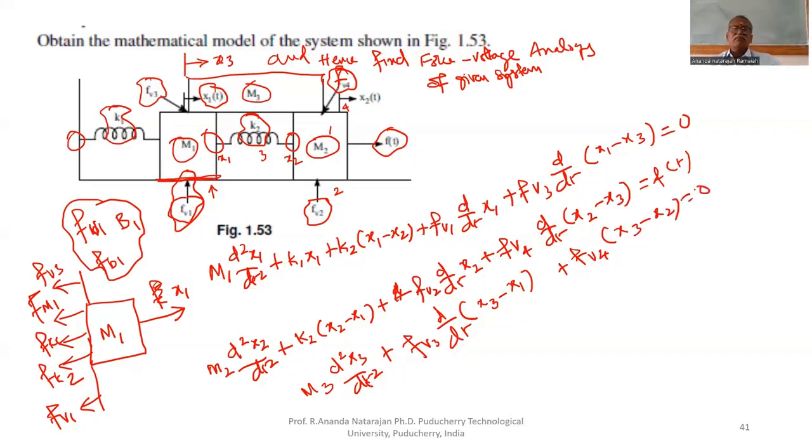No applied force. Only three reaction forces. Now we got the mathematical model of the given mechanical system in time domain. These three equations together represent the given mechanical system.